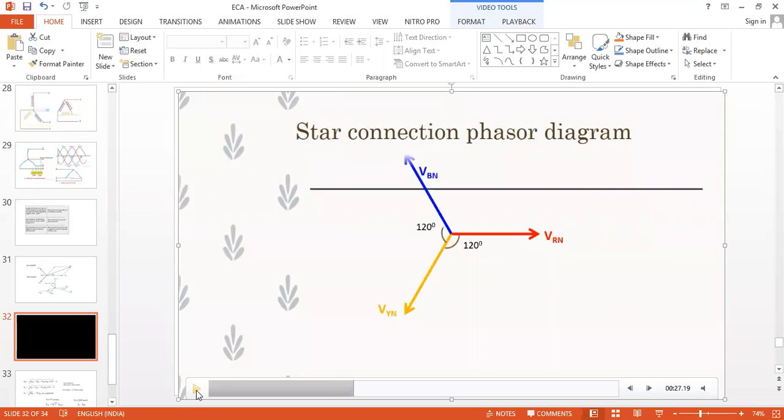You can see three voltages, phase voltages. So when we call phase, you can write here VPH, VPH, VPH, or you can write VRN. The voltage present between line and neutral, R line and neutral, is called the phase voltage. So what is the first statement? Star connected system contains three different phase voltages which are displaced by an angle 120 degrees. Okay. Now let VRN, VYN and VBN be the phase voltages which are displaced by an angle 120 degrees. As it is, you have to write.